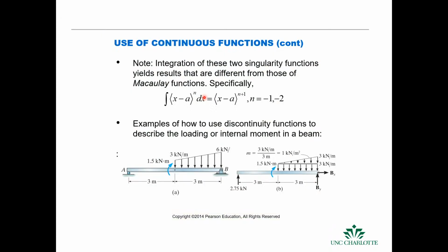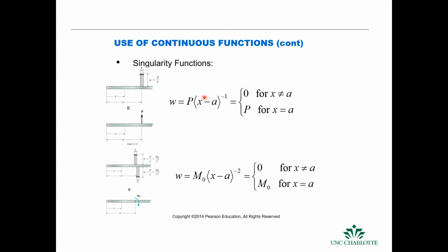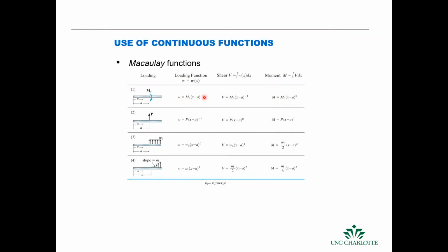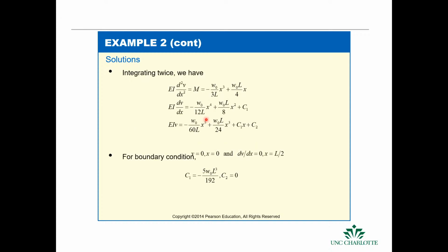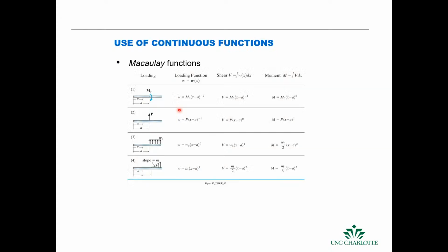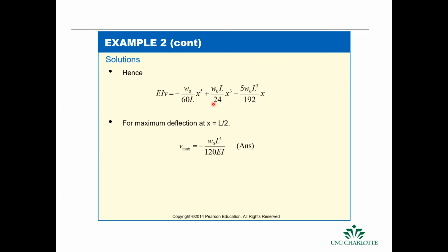But I think what we'll do is we'll cover the singularity functions and how we can use those to represent different loading conditions instead of using the integration. So for now, we have this method which works, where we can introduce, based upon the moment equation, the elastic curve and solve for the deflection and slope. I'm going to show you how to do this also with the singularity functions, which I will show you in the next lecture. So I'll stop here.